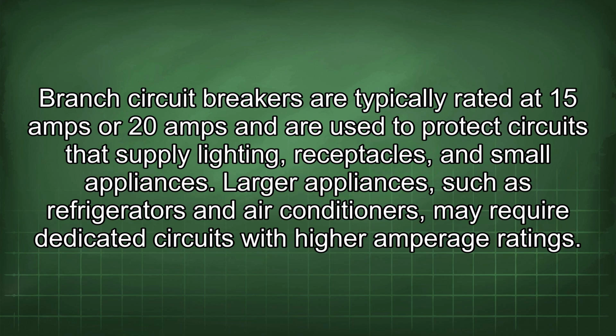Branch circuit breakers are typically rated at 15 amps or 20 amps and are used to protect circuits that supply lighting, receptacles, and small appliances. Larger appliances, such as refrigerators and air conditioners, may require dedicated circuits with higher amperage ratings.